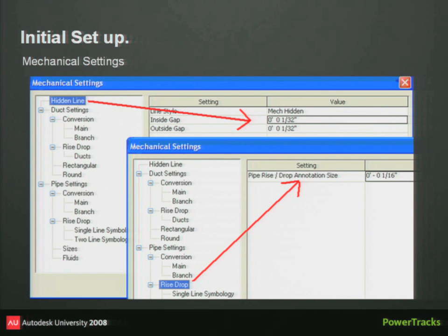But this is important starting from step by step. Let's say from unit setting. In unit setting, you can set up that maximum numbers. Like you can go up to, for instance, 1/16, and you cannot have an option of setting a 1/32nd. So it's kind of important that in initial unit setting, you make sure that common length unit setting can handle up to 1/32nd or even better. So I think the default setting is like just 1 inch, which is not going to work in this case. So that's kind of an important factor.